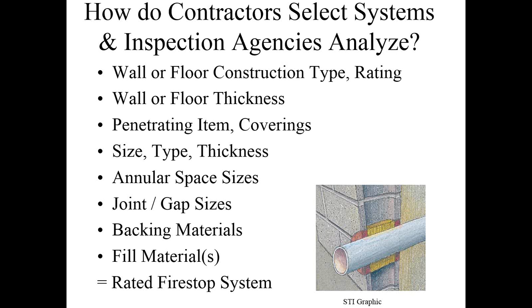Why? Because if there were holes in the slab, then the fire attack could come from two sides of the assembly. The fire test, the ASTM E119 UL 263, does fire attack only from one side of the assembly. Therefore, from a structural perspective, the assembly may not make it the length of the fire test if it's got fire attack from two sides. That justifies the need to maintain the continuity of that fire resistance rated assembly from both sides. Great question. Really appreciate you asking it.